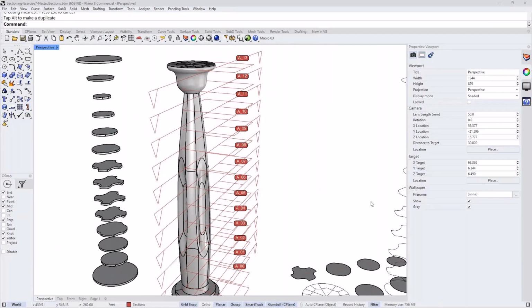I apologize. If we look at the previous exercises that we did, let's say I'm working on a sculptural form and I want to subtract a section, then I can use the clipping plane and set the function extract, and then it will slice it. So the plane becomes a slicer.